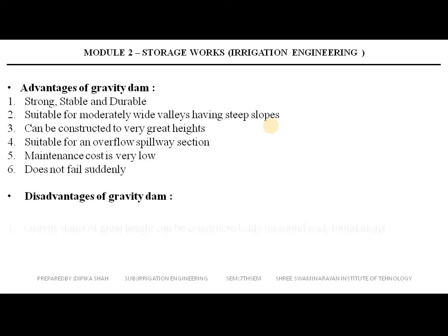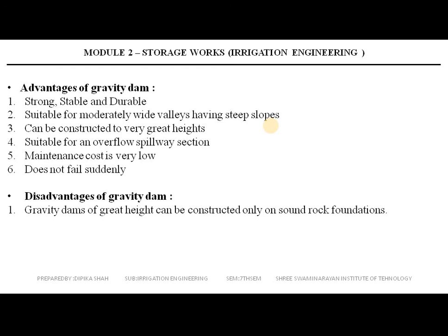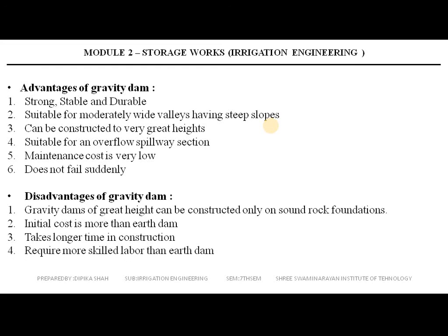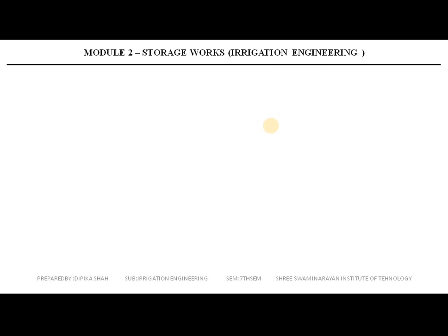So in a disadvantages, first is a gravity dam of a great height can be constructed only on a sound rock foundation, right? So sound rock foundations are required. Initial cost is more than a earthen dam. Take a longer time in a construction, mechanized plants for manufacturing and transporting concrete are required, more skilled labor than a earthen dam, and it is very difficult to allow a subsequent rise in a